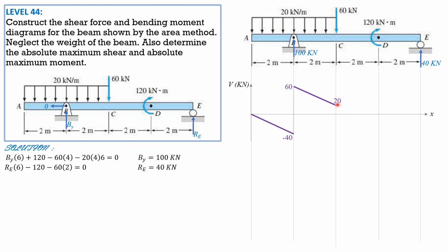Then minus 60, so negative 40 here. Then there's no change in loading, so horizontal. Then that's moment or couple, so horizontal. Then it closes because we have 40 there. So this is the shear diagram after shading.